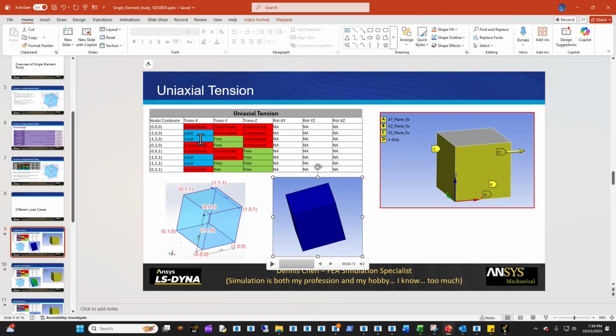So if you follow all of that, what I did here is a much more indirect way, but some codes require you to define the nodes by the XYZ constraints. So it's not going to be as easy as Workbench. Workbench makes it easy for everybody. You just have to assign some surface level constraint and you're good to go. Some other code like Dyna, for example, will ask you to constrain the nodes individually. In that case, you can sort of see the basic constraint that you're doing is, if you follow the 0, 0, 0, 1, so I basically rotate this way and rotate this way as you go down the list.